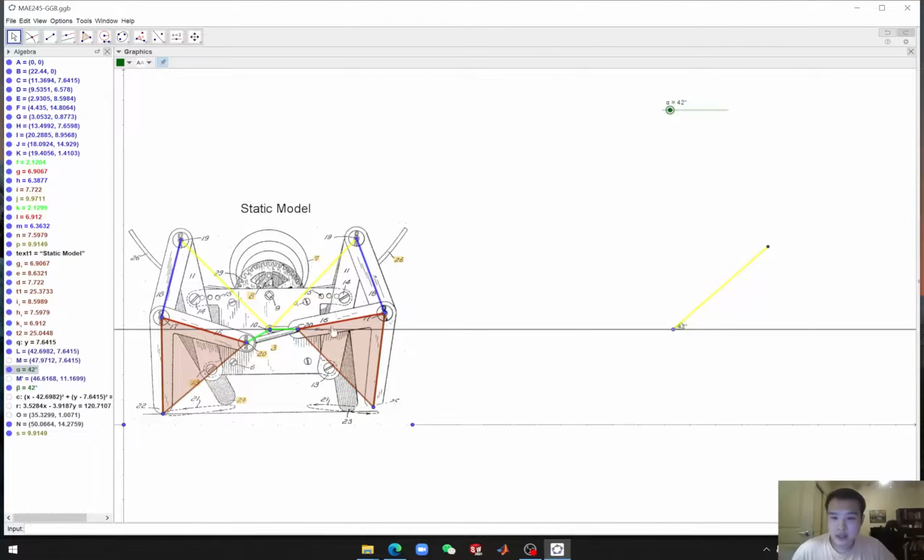And then the next step, we can project the green link, also the input link. So basically do the same thing, but because the input link is also rotating, we need to add another slider. Can do the compass first, and oh wait, I don't need a new joint.